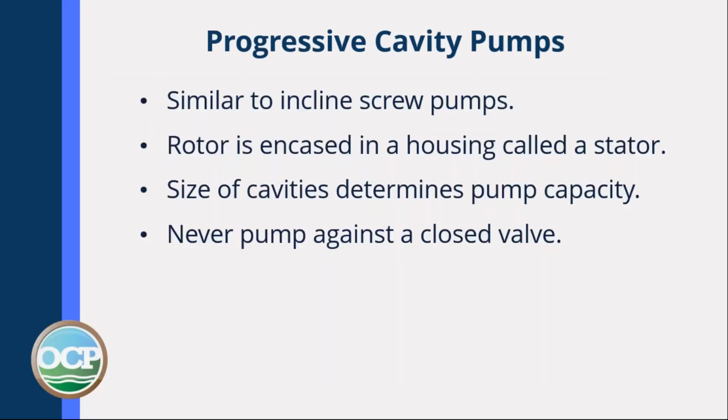You have progressive cavity pumps. They're similar to incline screw pumps. The rotor is encased in a housing called a stator. The size of the cavities in the rotor and in the stator determine the pump's capacity. Again, with these, never pump against a closed valve.